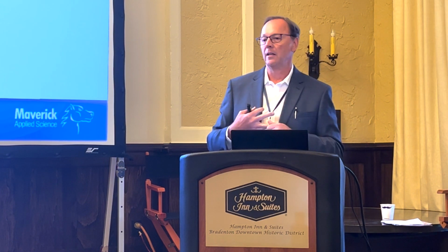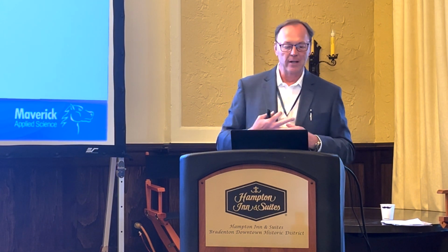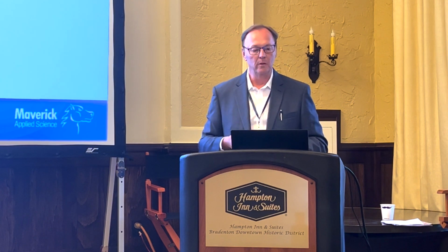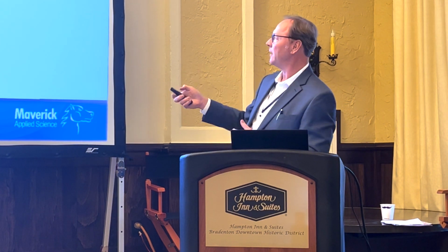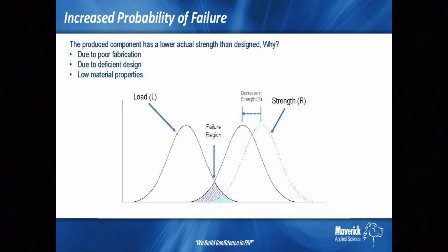Deficient design, those sorts of things I mentioned earlier. Low material properties. Again, we're reducing the strength here, so we're bringing this curve closer. Now we're going from a 5% chance of failure to maybe 15 or 20%. This is when we get NCRs and you say, okay, accept as is.